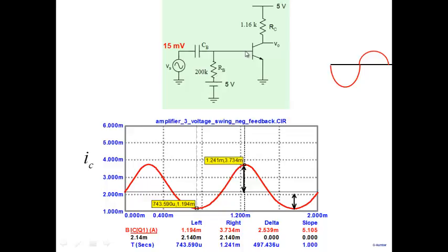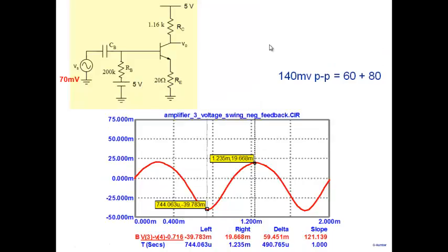So between base and emitter, by some means, if I could apply a distorted sinusoid, then this distortion will get cancelled by the transistor's distortion, and at the output I'll get a nice sinusoid. At the output, the two distortions will cancel each other. Now you must be wondering, I have a pure sinusoid. From this pure sinusoid, how do I get a distorted sinusoid such that this distortion is cancelled by the transistor and I get a pure sinusoid? Well, the answer is actually very simple.